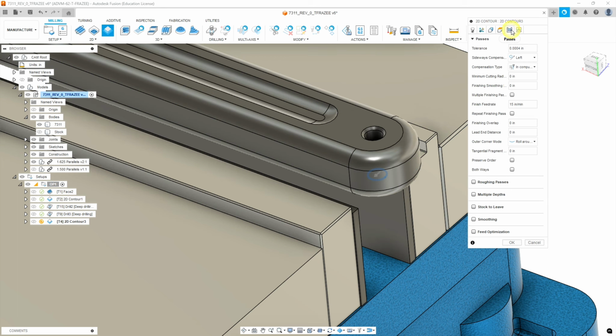Okay, now we're going to go to passes. And typically I have this set to wear, which allows the operator to make changes based off a stock diameter tool. We're going to switch this to in computer, and the reason is there's not enough room for us to have a lead-in move with a 1/4 inch end mill doing this. If we were using an 1/8 inch, which had more room to move around in here, we would, but we're only taking 3.5 thousandths per side off.